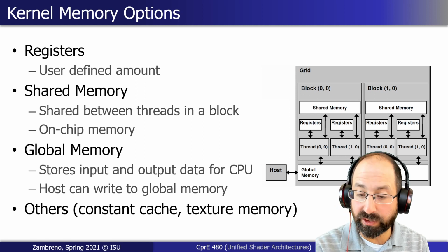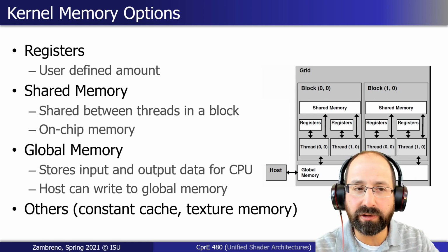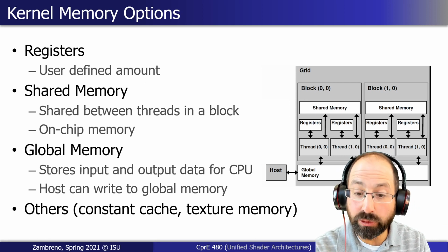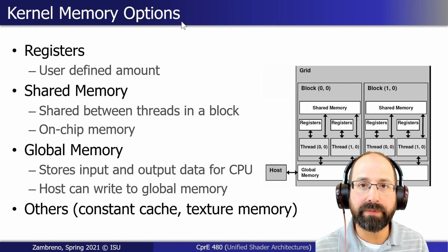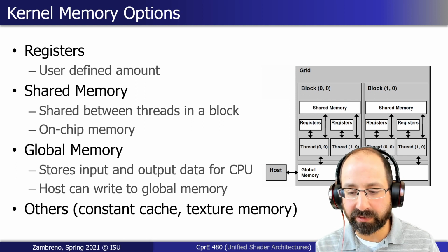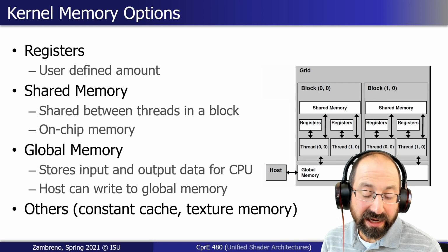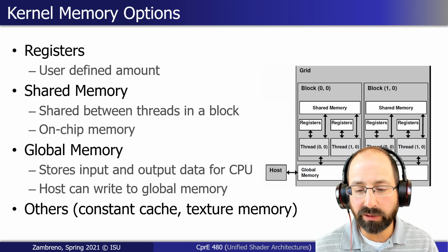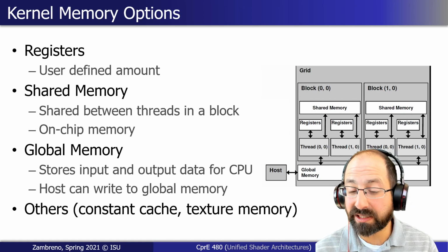But if you do have a use case for that, and there's all sorts of examples that show interoperation between rendering code and compute code, then using that would be more effective than just putting everything as a big array in our device memory. From our lab implementation for our simple graphics processor, we're not doing too much with our texture memory, right? So there's a small advantage to our texture lookup versus a load store lookup for our SGP implementation, but it's a pretty small one, right?